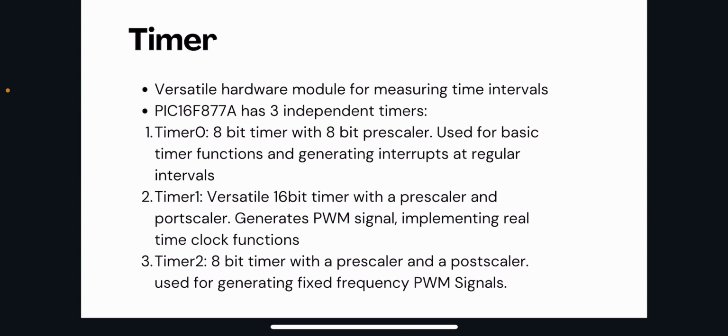Coming to the timer. A timer is a versatile hardware module for measuring time intervals, and our microcontroller PIC16F877A has three independent timers. Timer 0 is an 8-bit timer with an 8-bit prescaler. It is used for basic timer functions and generating interrupts at regular intervals.